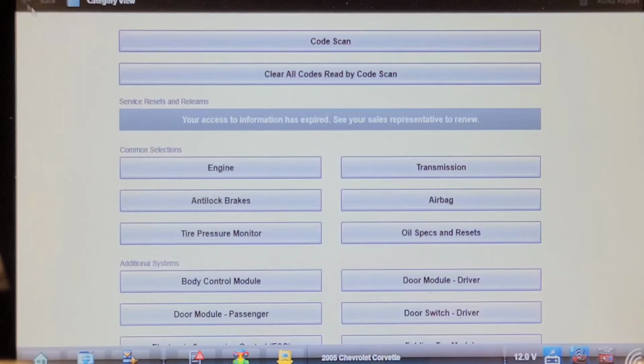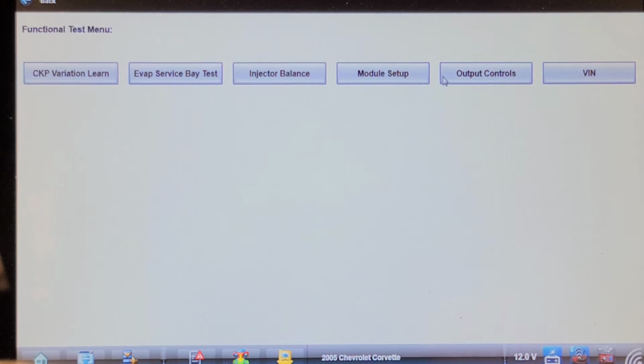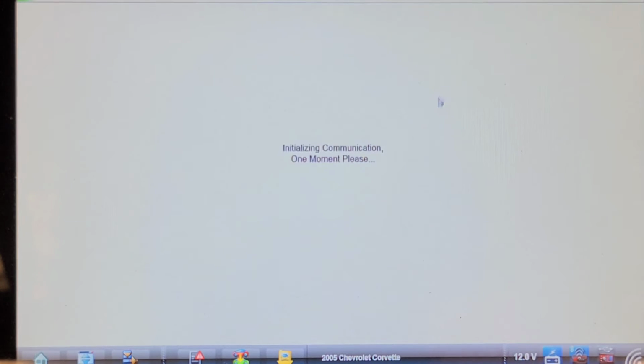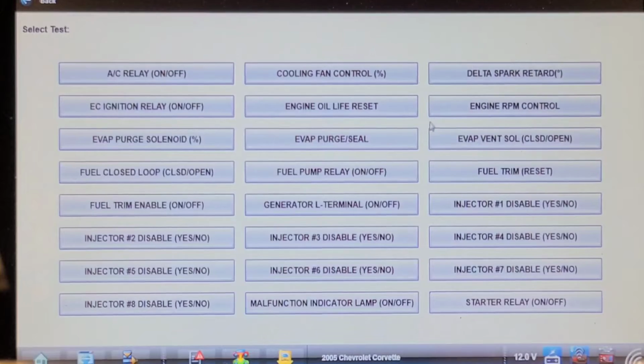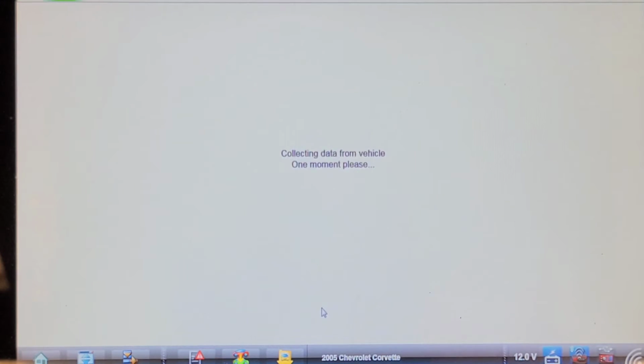I just realized that when I was turning this push button ignition on, I was putting it in accessory mode, not in run mode. So that's probably why I was still getting data, but the bidirectional controls weren't working. Of course, running it would work.